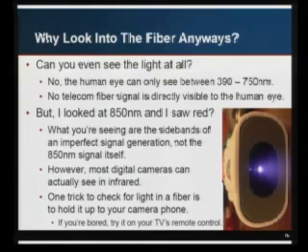Kind of a cool trick if you want to see if a fiber has signal or not is you can use a digital camera because they are sensitive to infrared. So here's an example of a digital camera taking a picture of a remote control, and you can see the light. So if you've got a camera phone, you can hold it up to your fiber and you can actually see light coming out of there. It's a quick and dirty trick to see if there's signal.